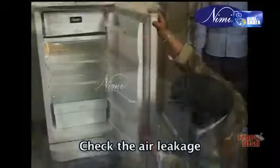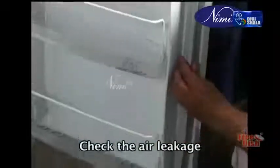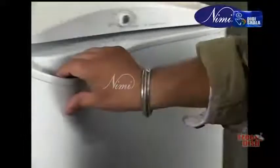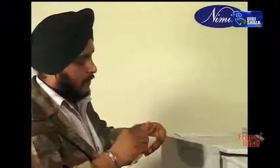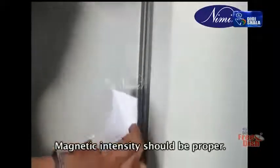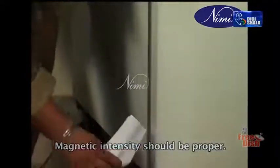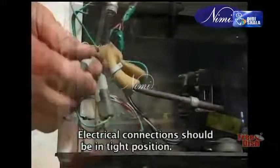Check the door gasket for any air leakage. Magnetic intensity should be proper. Electrical connections should be in a tight position.